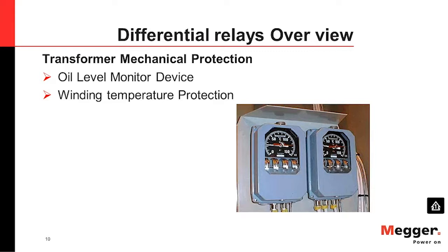So it depends on the location. You may have a trip or you may not. But internationally, yes, the fourth stage of the winding temperature will give a trip directly to the breaker.